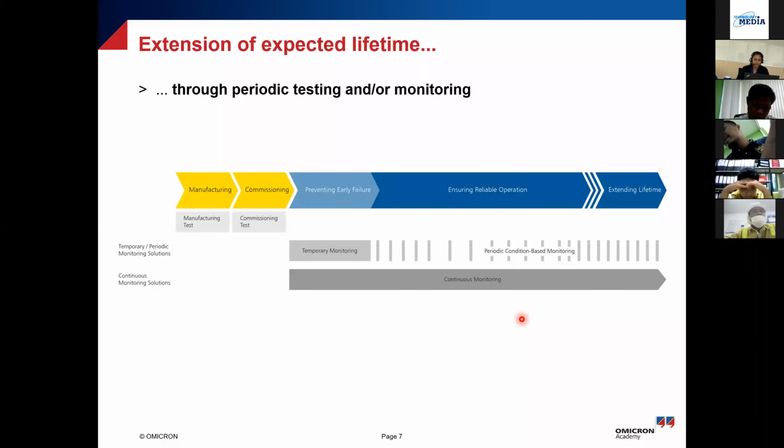So if we talk about the service life for your machine, you have the initial factory stage. If you want to avoid these teething problems, like the infant mortality rate, the concept comes much before that. So you should know what factory tests are being performed, because utilities specify these factory tests. There is no hard and fast rule as to what tests are to be conducted. Yes, some tests are mandatory, but not all tests are mandatory. So it has to be your choice that you specify these tests are mandatory for my particular machine.